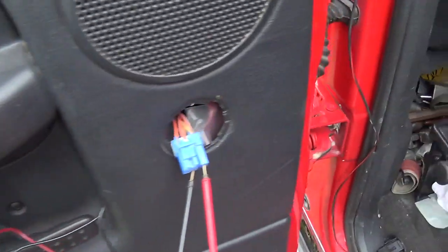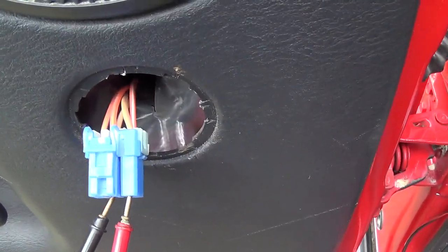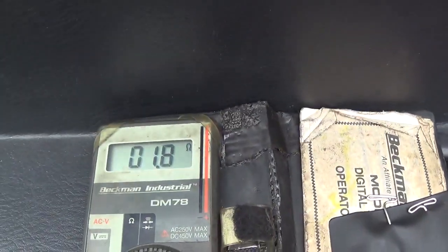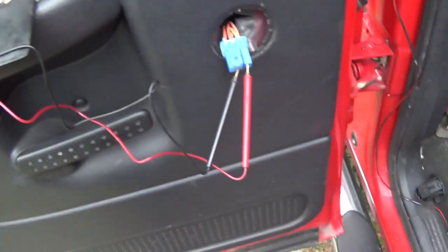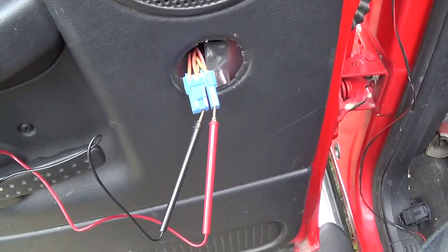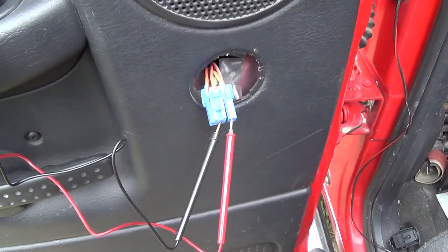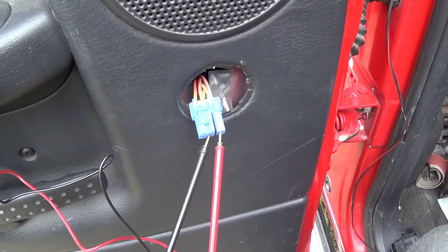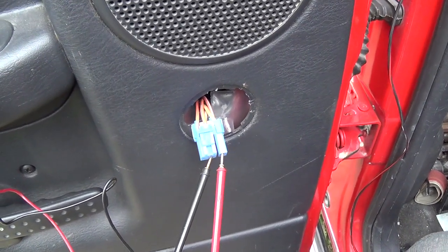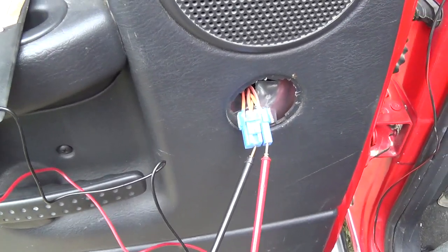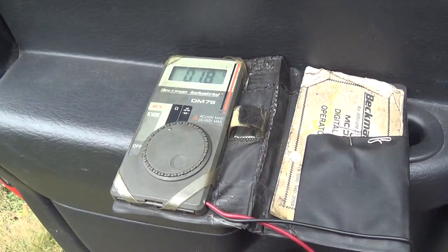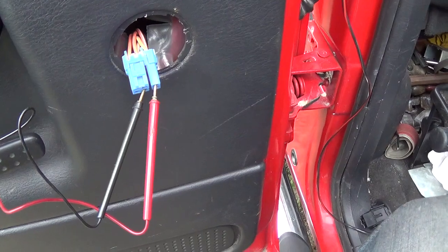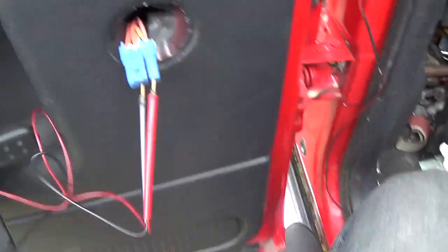So I'm measuring across the motor winding. See the tan yellow and then the tan and blue wires right here. We have 1.8 ohms. So interesting. I thought I'd see an open or something. I don't know if we had any current going through there. Very peculiar. Okay, so 1.8 ohms. Now I'm curious if we just give this motor some power, if it'll work. That'll be like a bypass test.